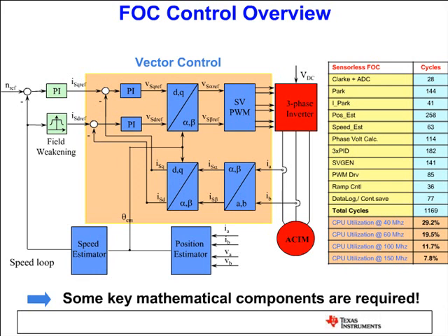I'm talking about Piccolo A and Piccolo B devices, 60 megahertz devices, which means that we can control up to 4 sensorless PM motors instantaneously. And what we did, we controlled 2 motors plus PFC. PFC is at 100 kilohertz, and the switching frequency of the motors is 10K. And 2 motors plus PFC is using like 65% of CPU. Again, we have like 35% room for the customer for background and slow tasks, protection, system monitoring, keyboarding, and some other functions.